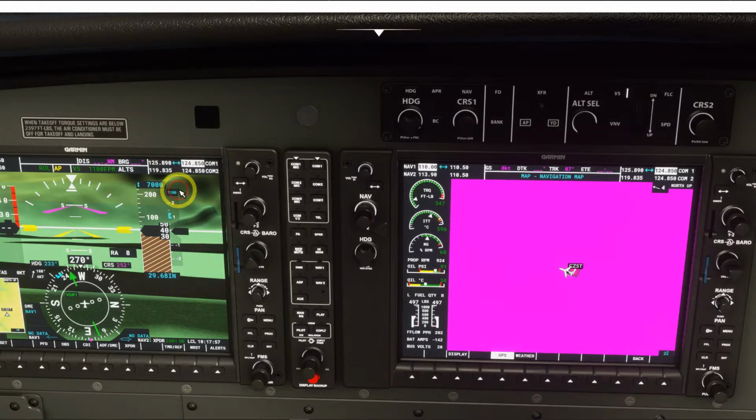And here will give you the full speed, the vertical speed that you have selected. Once you activate all that on the autopilot and you press the autopilot, it will start pulling the aircraft up or down, and that black triangle will start adjusting to wherever this bug, the vertical speed bug, is.